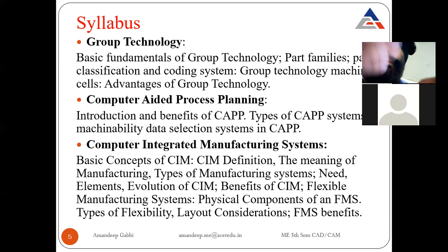First, you have to make the edges, then drill a hole inside. Then you have to thread it from inside. So these are three different processes that are to be done on a particular nut. So computer-aided process planning will decide which operation has to be done prior to what. Which operation should be done first and which later. So with the help of CAPP, we will decide which operation will be done earlier and which operation will be done afterwards. So computer will tell us about that.